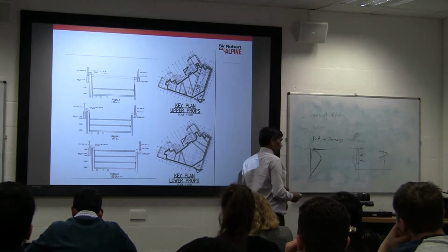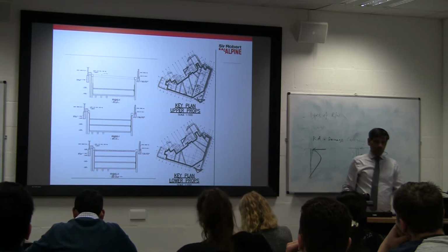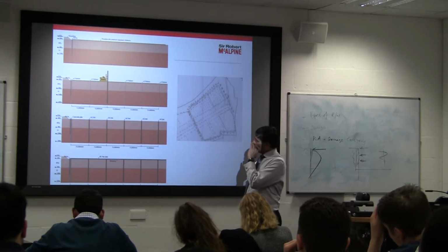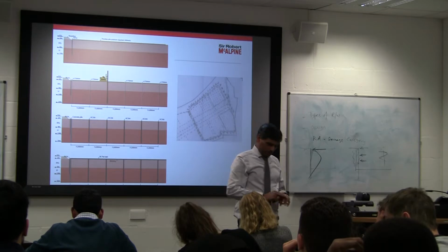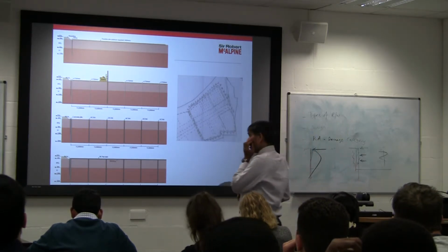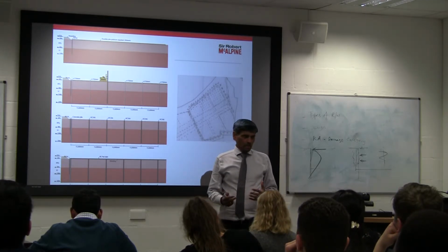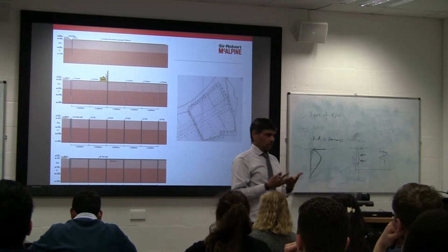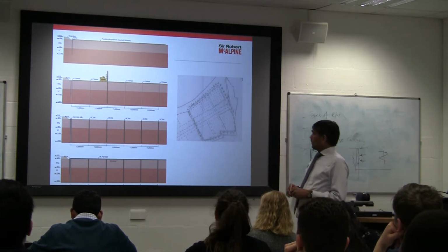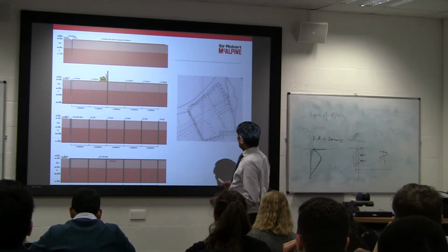So what happens is, in that scenario, you've got a multi-strutted excavation. Not single level, but multi-strutted. So that's all right in terms of a bottom-up blue sky option. Sometimes, what happens is, it takes a long time to dig it out, but I want to progress on the top in construction terms. So how do we do that in that case? Because the volume that we are excavating is so huge.